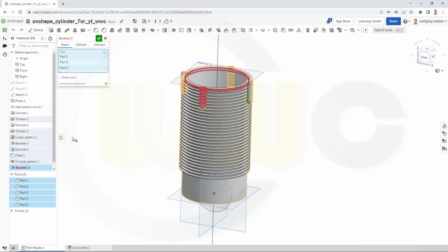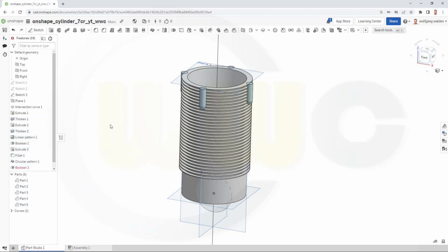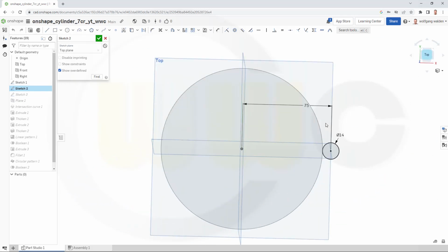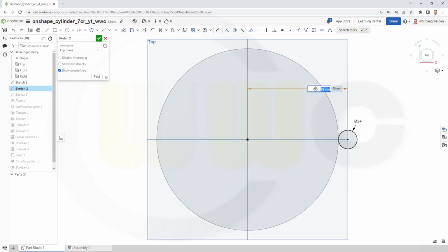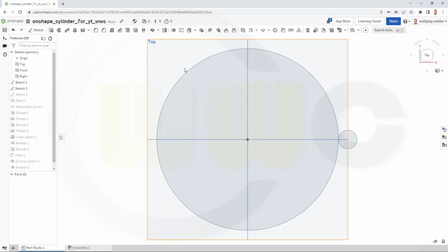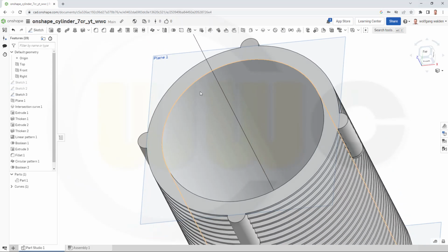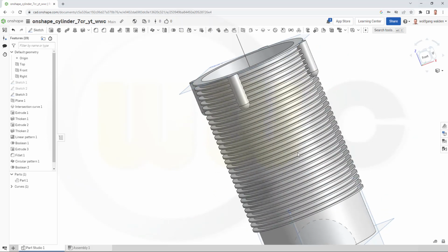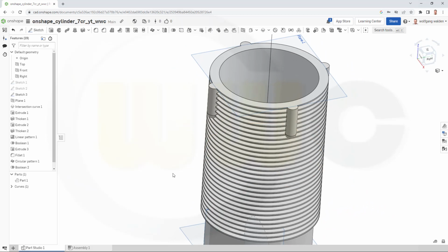Didn't work because it's parasolid. So we have to change that, sketch number 2. So that dimension here should not be 75, but 74.999, for example. Otherwise, those solids would touch that solid here only with a line, and that's not possible in parasolid based software.